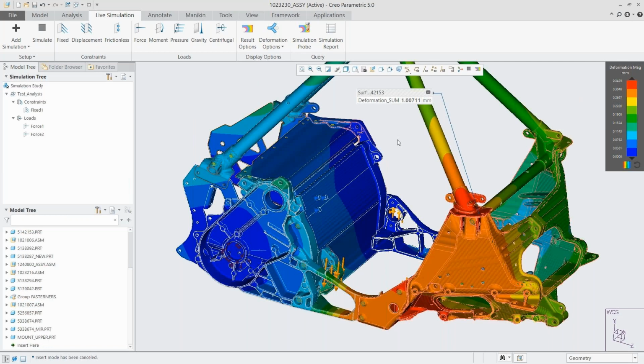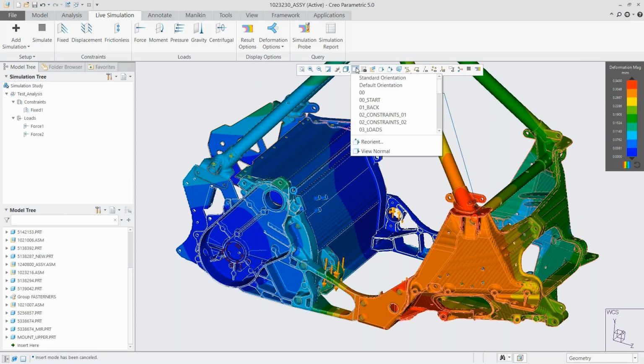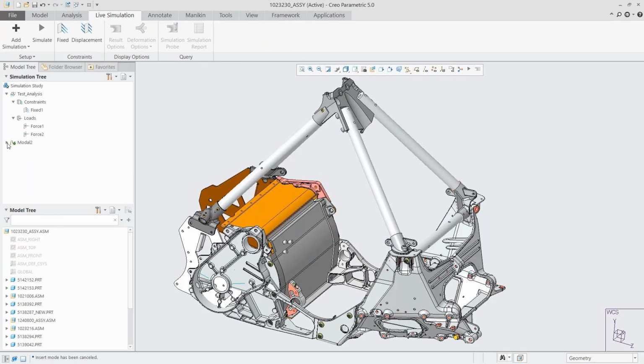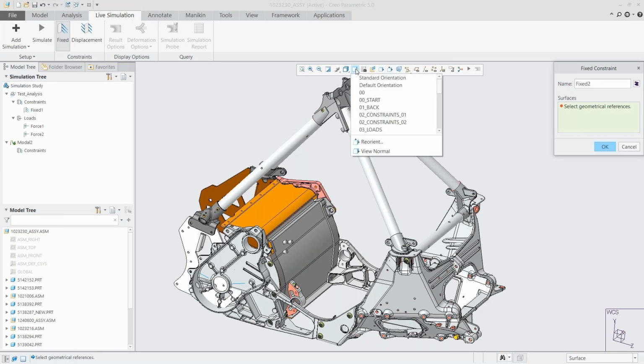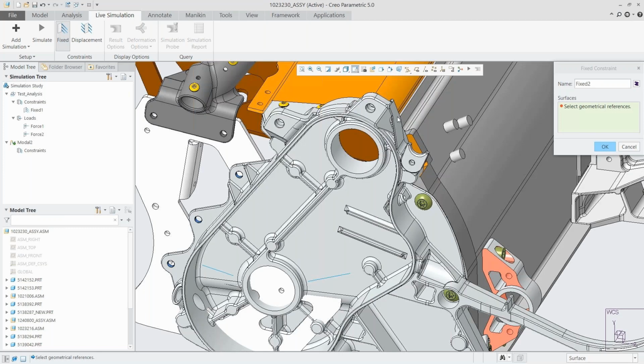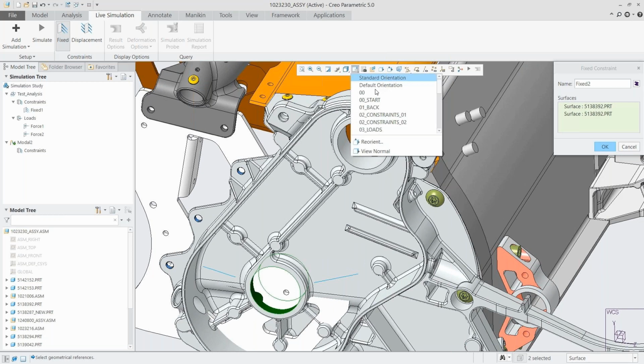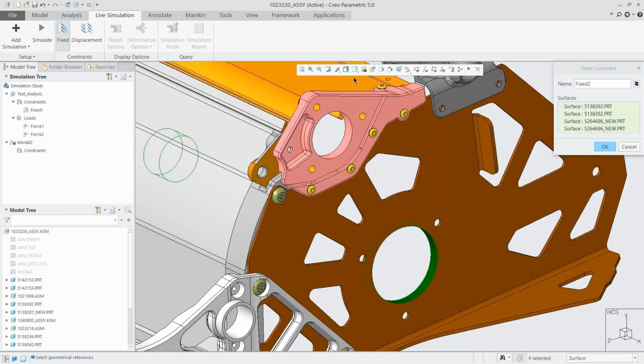Okay, and as soon as we added those different parts, we see the simulation completely updates. We see that new value right up on the screen there. Okay, and that's the basis of what we're running through with one of our structural studies here. We also have some other options like I mentioned earlier. So let's look into maybe more of a modal study. So maybe we have a certain vibration that we want to take a look at here. Well, it's going to be similar to how we started with the structural analysis and laying that out with those parameters. We can essentially say what parts we want to be fixed and then what parts that we want to study here.